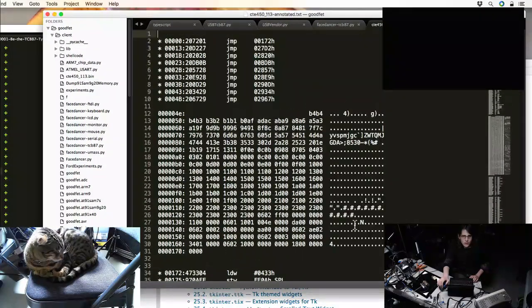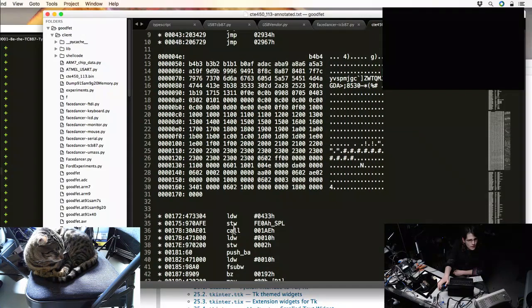So the kind of manual step that I went through using that terminal, but without all the slowness, was to roughly separate out code and data. So the interrupt vector table, for example, it's a little tight because you have all of these separate little instructions that are separated by a random amount of space. So I just ignored the space between them and got just the jump instructions. And down here, I forget what this is, but I think I saw a pointer to it that indicated this was a data table. So I just hex dumped it.